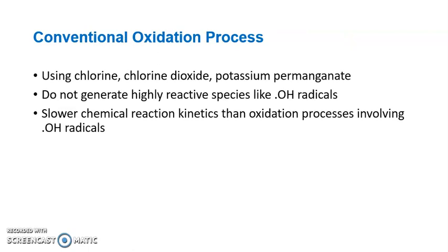So I mentioned the conventional oxidation process when we were using chlorine dioxide or potassium permanganate for water disinfection. We were conducting the oxidation process. They didn't generate very reactive species like hydroxyl radical, so they were slower chemical reactions compared to the advanced oxidation reactions. I'm going to discuss the advanced oxidation reactions. The advanced oxidation reactions involve the hydroxyl radicals, so they are so fast and they have several advantages compared to the conventional oxidation processes.